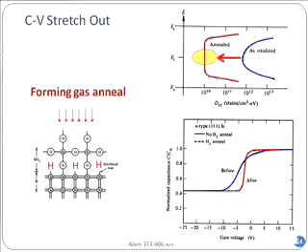And you can see that before, you have a strange CV curve that has the accumulation on the right hand side up to a particular value. Do you notice that C divided by C naught is equal to 1, because in accumulation the charge is just sitting next to the oxide, so that's why you have 1.